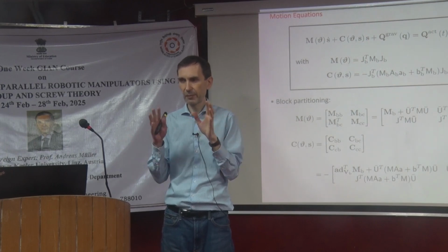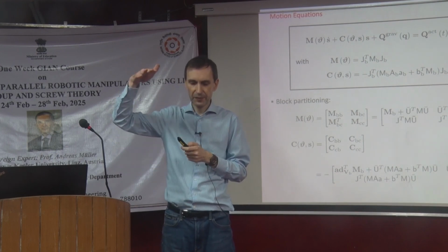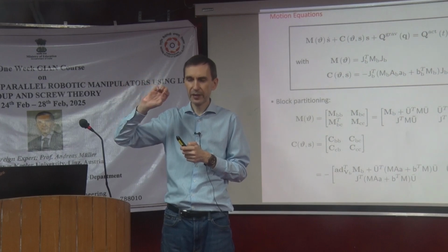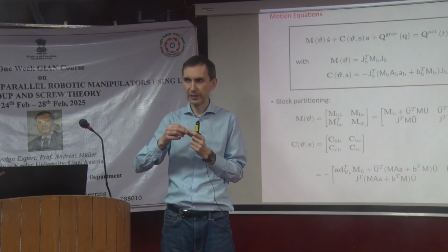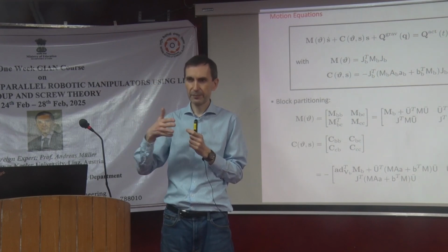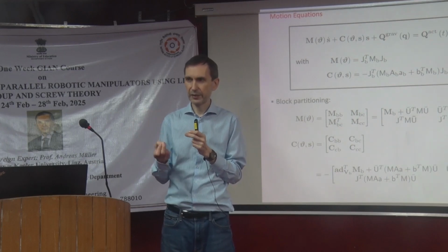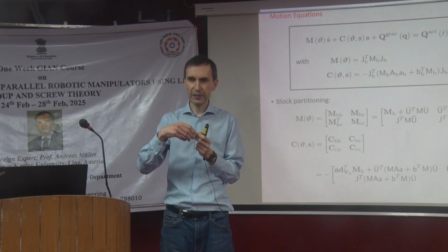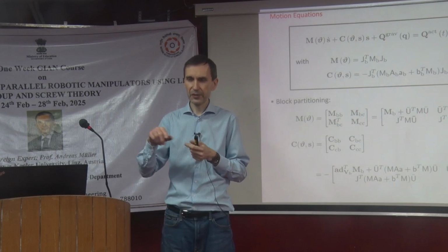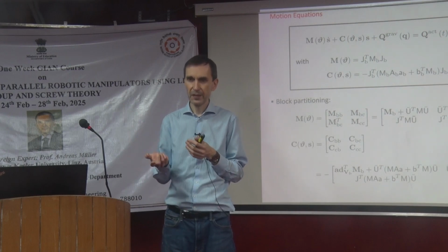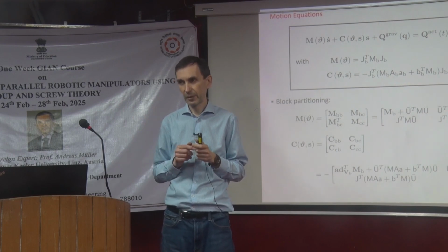Because the masses, the inertia parameters, you have identified before. The chain is like, first of all, you have to calibrate your system. Calibrate means kinematically, geometrically calibrate, just to know that you are exactly at the pose where you want to be. Second, you have to do the dynamic identification. So you do persistent excitation, high-speed motions, and then you measure the torques, and then you identify the mass and the inertia. Once you have all the inertias, then you can go and identify stiffness and damping.